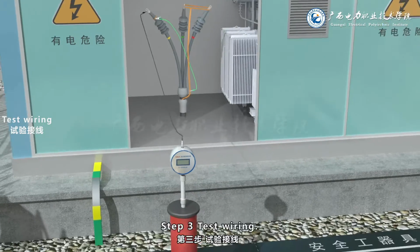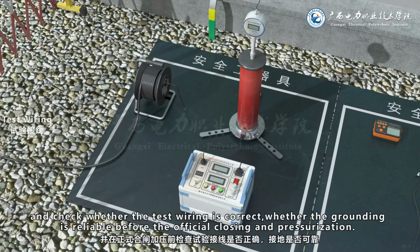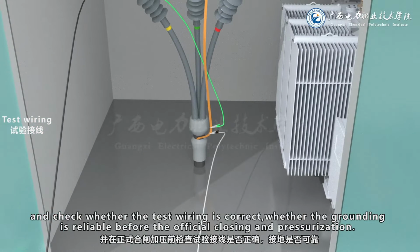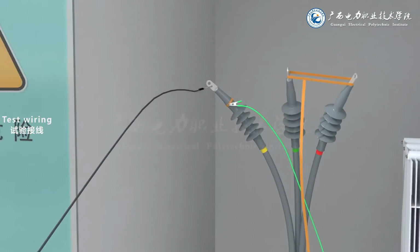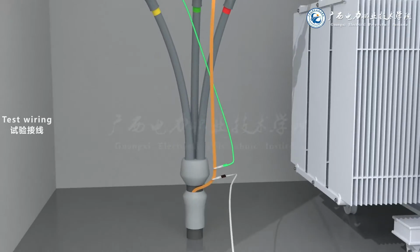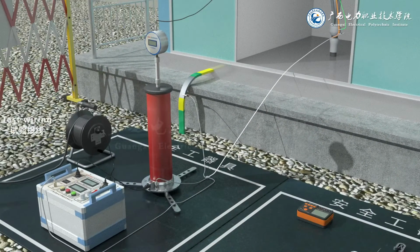Step 3. Test wiring. The person in charge of the test shall connect the equipment and check whether the test wiring is correct, whether the grounding is reliable before the official closing and pressurization. The pressurization test can be carried out only after confirmation. Pay attention to that when testing one phase, the other two phases are grounded, and ensure that the grounding is correct and reliable.